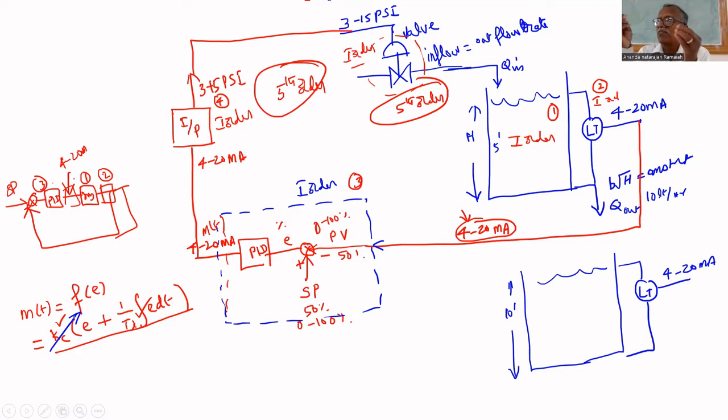At the same time, if you give a very small value, it takes a long time to adjust to the level. That is also not acceptable. Suppose I am asking you to solve a sum that should take 5 minutes, and it takes 1 hour to solve. Is it acceptable? It should be done quickly. At the same time, if you increase Kc beyond a certain value, it becomes unstable. That's why you cannot increase beyond a certain value. At the same time, it has to be done in a reasonable time. That's why we have to find a compromise between the two.